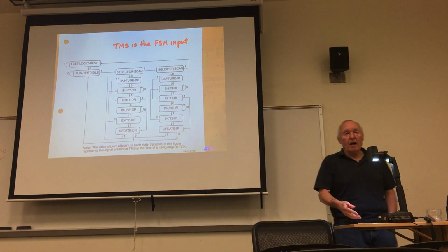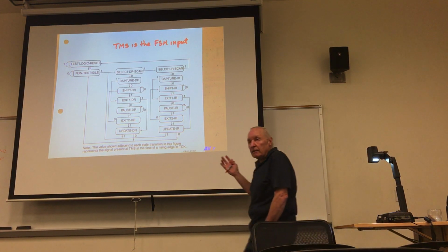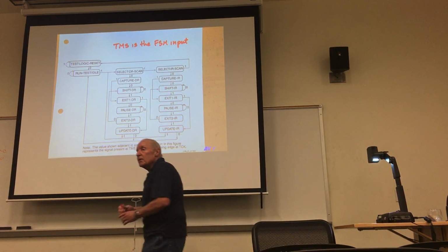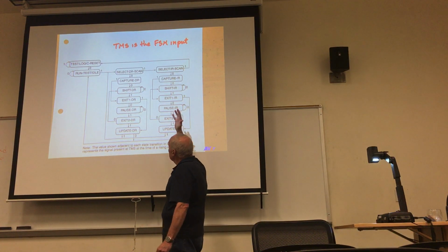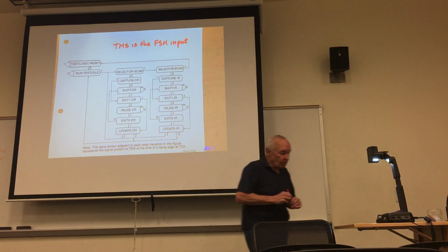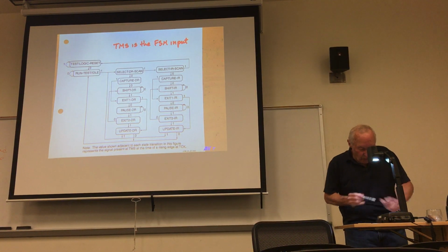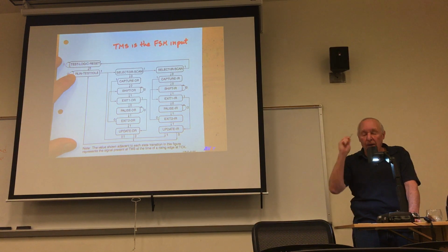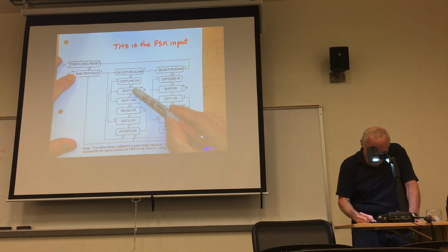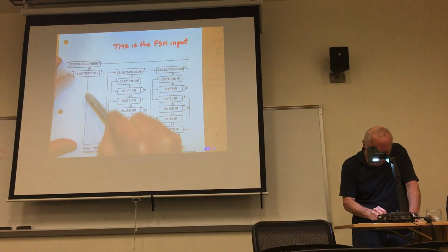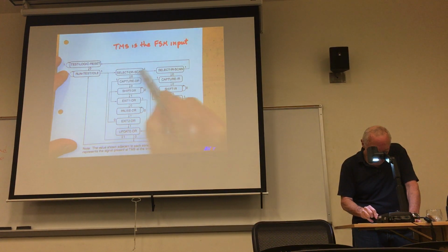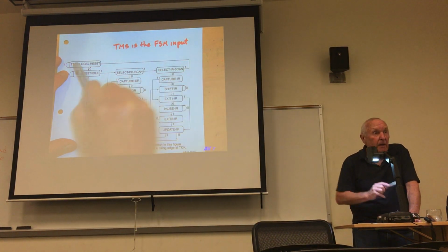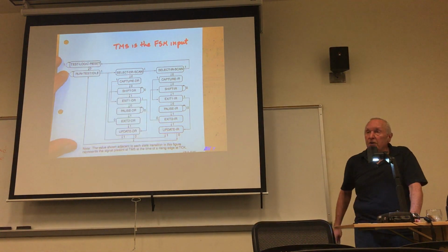When I first powered this thing up, I could be in any state. Pick a state, other than the initial state. Shift DR. So let's suppose the thing came up in Shift DR. I'll set test mode select equal to 1 and give it 5 clocks. 1, 2, 3, 4, 5, and I'm in test logic reset.